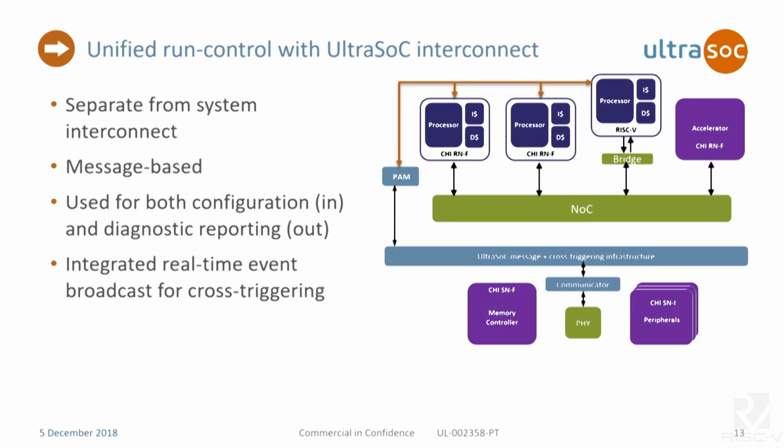So first, we need a run control. And the run control that we have needs to support the various different kinds of interface to the cores. You don't want one for ARM, one for RISC-V. So you need a unified approach. The interface coming in from the outside world may be different to the interfaces that the cores have, so the blue structures need to abstract away from that.